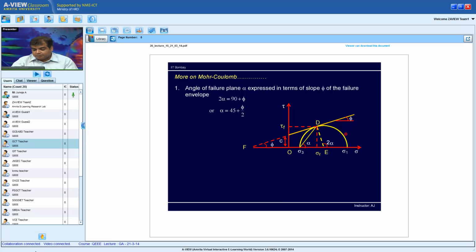If you look at this Mohr circle over here, I have this alpha starting from the origin, and this broken line intercepts the same point. So if this is alpha, elementary trigonometry tells me this angle should be 2 alpha. Okay, so I have 2 alpha over here, and inside would be 180 minus 2 alpha.